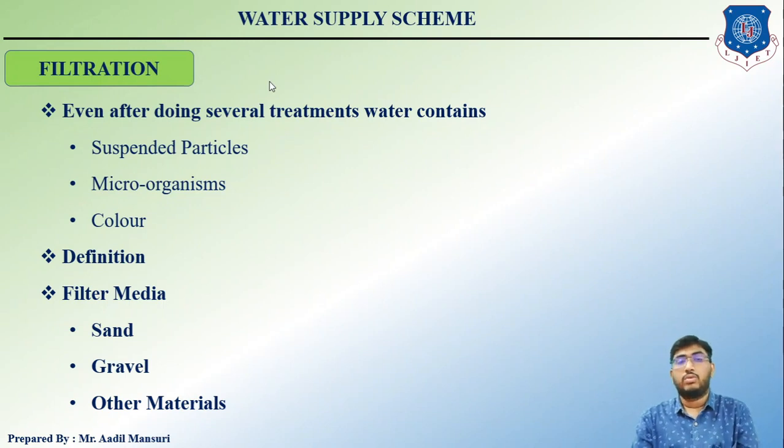Okay. Now, talking about gravel, the sand beds are supported on the gravel bed. Okay, so the layers of the filter are like this: the topmost layer will be of sand, then beneath the sand layer there will be a gravel layer. The gravel used should be hard, durable, free from impurities, properly rounded, and should have a density of around 1600 kg per meter cube.